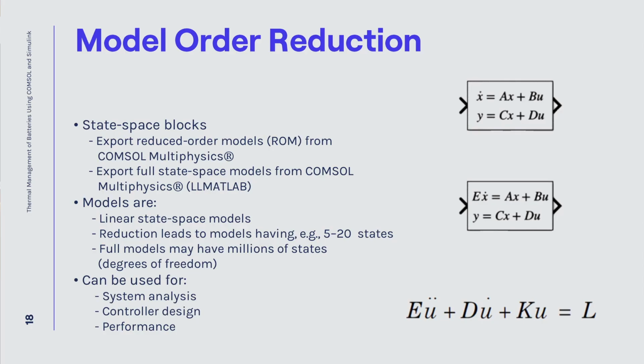Okay, and besides this cost simulation, model order reduction is also possible. So if you want to simply reduce the size of your model, that's also possible. You can use this reduced order modeling technique, and you can export that into MATLAB or Simulink, and you can run these models using much fewer degrees of freedom. So they will run much faster than the original full fidelity finite element model.